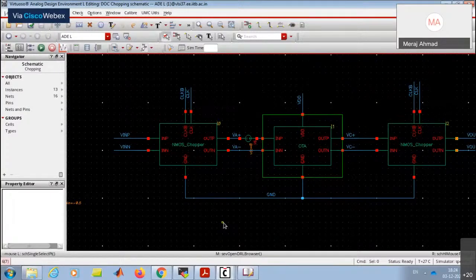That's why we say that we are able to achieve microvolt level of accuracy. If these issues were not there, we could have got accuracy in nanovolts. There are people who have reported that with the nested chopping technique, offset can reach 200 nanovolts easily. So to address the clock injection and charge injection problem, there is a technique called nested chopping. If you can read those papers, that will be pretty clear. The simulation setup will be exactly the same. We will copy this module, add one chopper here and the next chopper, and have a different clock. So the simulation setup will be exactly the same.